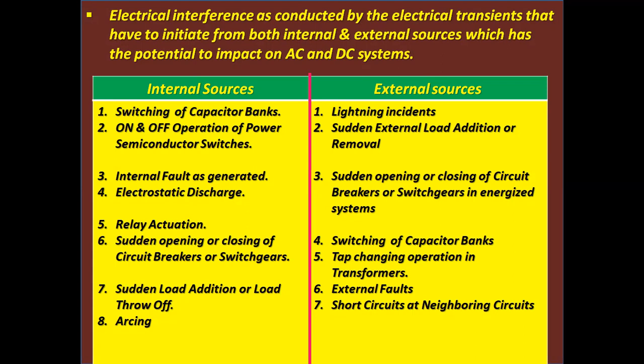Internal sources: that is switching of capacitor banks. Number two, on and off operation of power semiconductor switches. Internal fault as generated. Electrostatic discharge. Relay actuation. Sudden opening or closing of circuit breakers or switch gears, sudden load addition or load throw off, and the last one is arcing. This is all the internal sources.